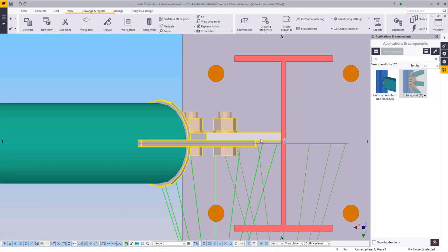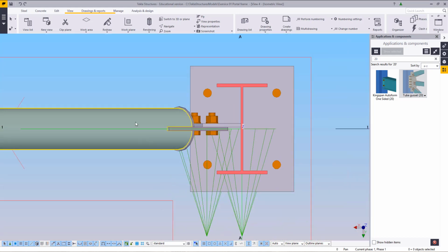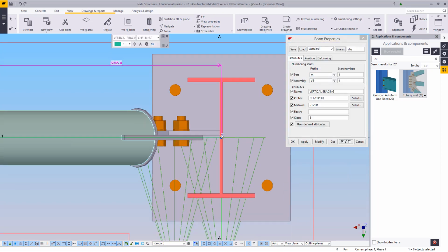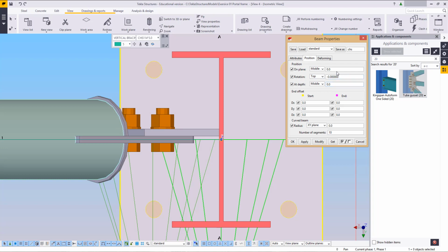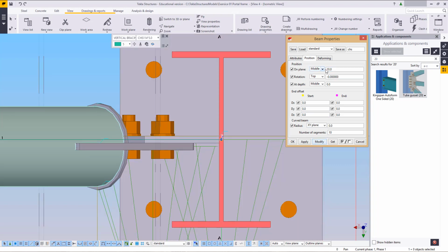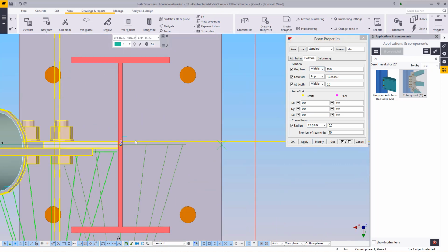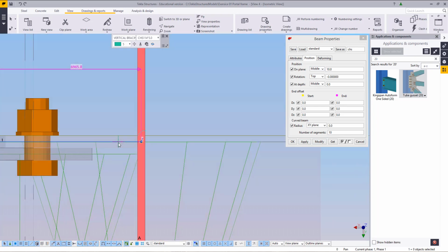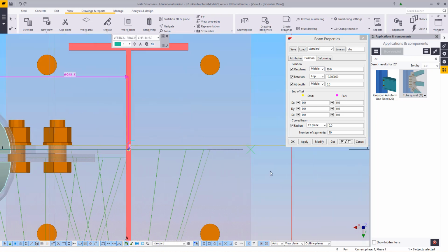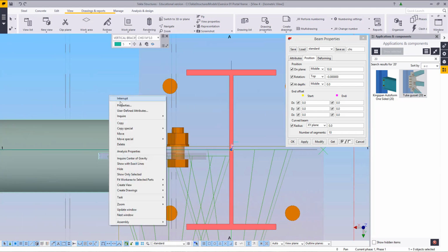Now, on to making the change. As I said, you can simply just move it. Personally, I prefer doing this on my position settings, giving either a 10 or a -10. In this case 10 is fine, gives us nice and centered. Let's make it see-through, and we can see our grid line right in the center of that gusset.